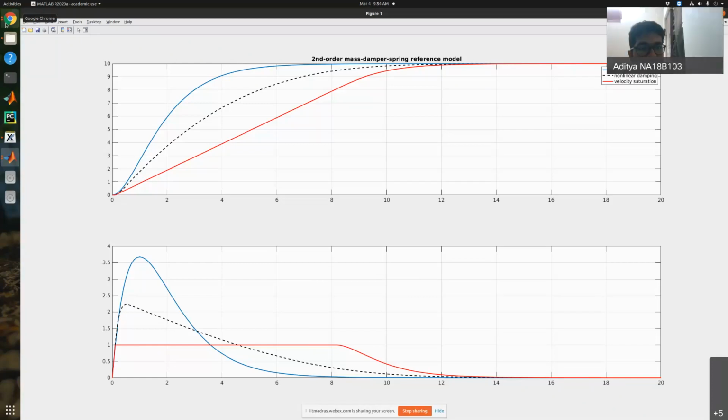We know what the power is. If I divide the power by the maximum thrust I can generate, I know what the maximum velocity I can achieve is. So these kinds of calculations will be done beforehand. These are back of the envelope calculations which we might want to do ahead of time.